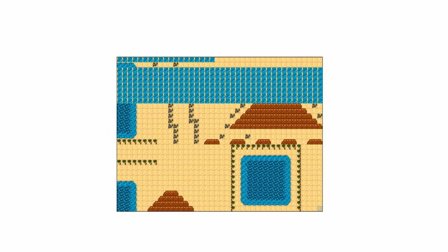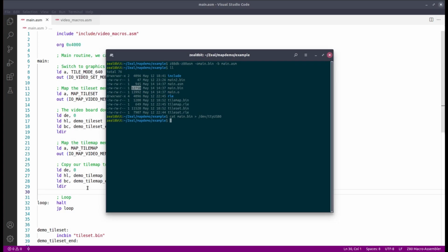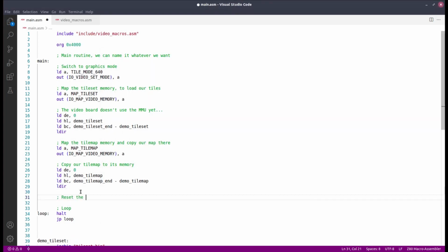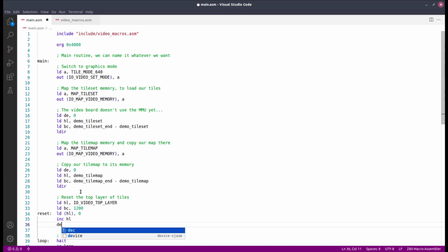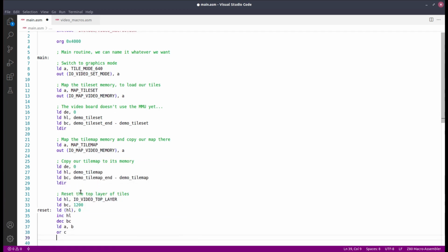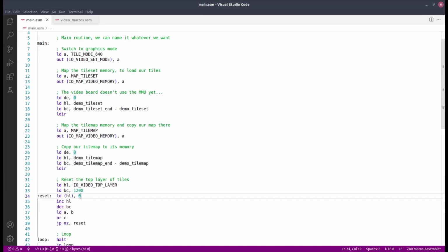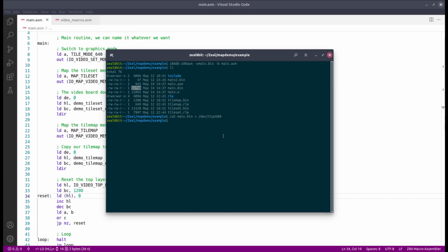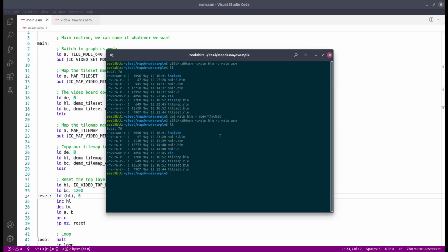This is our bug. So now we first need to reinitialize this array, or reset this array directly inside our program before the infinite loop. Let's do this. Okay, now it's done. We simply need to compile the program again, retrieve its size, and repeat the process on the board to send it through UART.